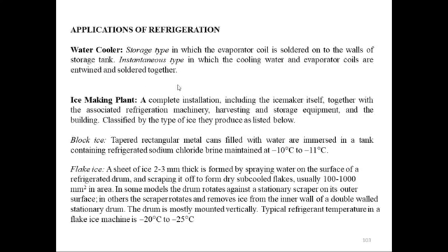So in water coolers, storage type, the evaporator coil is soldered on the walls of the storage tank. Instantaneous type, in which the cooling water and the evaporator coils are entwined and soldered together. So we have one such system installed in our NED University.